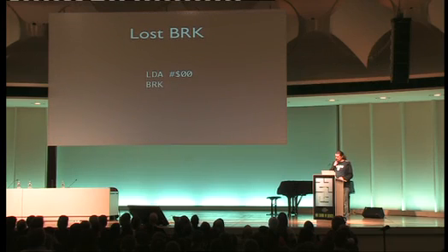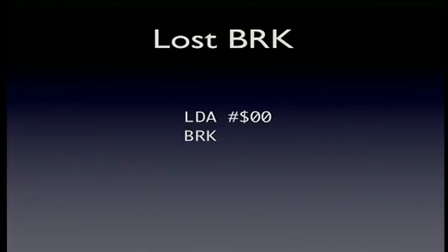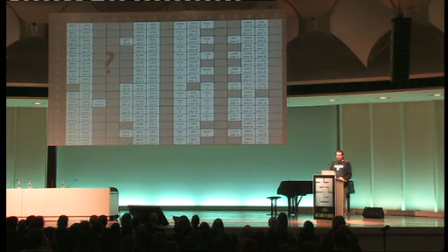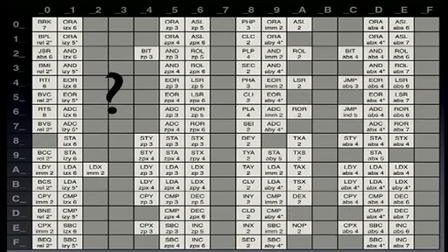This one is a real bug. If you have a break instruction, I mean, you wouldn't have it in real code, but in a debugger, you normally use it for debugging, and you put your break in if you want to know where your code went. But if you have a break in real code and an interrupt happens at the same time, then your break will just get lost. The break will not be done, just the interrupt will be handled. And there's this one big question mark here about illegal opcodes. This is the one thing that so many people have looked into.